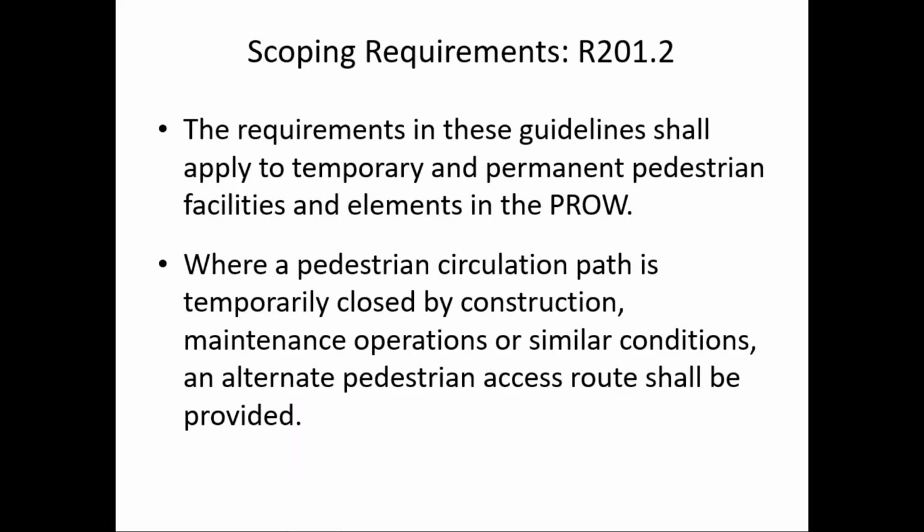In Chapter 2, Section R201 of PROWAG, they do address temporary traffic control. Notice the first bullet there is from R201.2. The requirements in these guidelines, meaning PROWAG, shall apply, there's that word shall again, shall apply to temporary and permanent pedestrian facilities and elements in the public right-of-way.